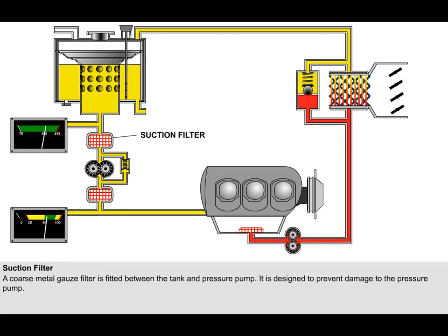A coarse metal gauze filter, known as a suction filter, is fitted between the tank and pressure pump. It is designed to remove particles of contaminant from the oil before it enters the pressure pump, and so prevent damage to the pressure pump.